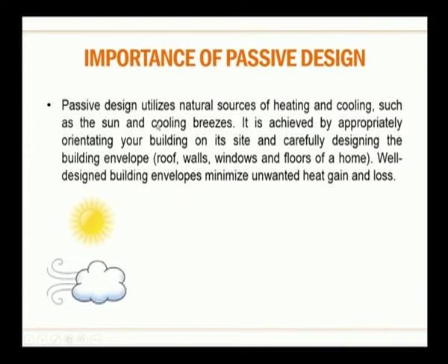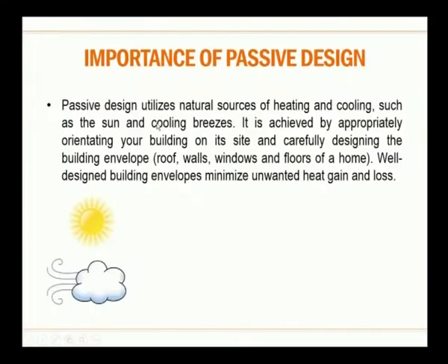So, when you start a design, you must know about the local climate, temperature bands, how many people are going to use the space, and what type of radiation the different devices going into the space are going to create. With all this theoretical information in hand, we can place each and every detail correctly, which will reduce the heat loss or heat gain.